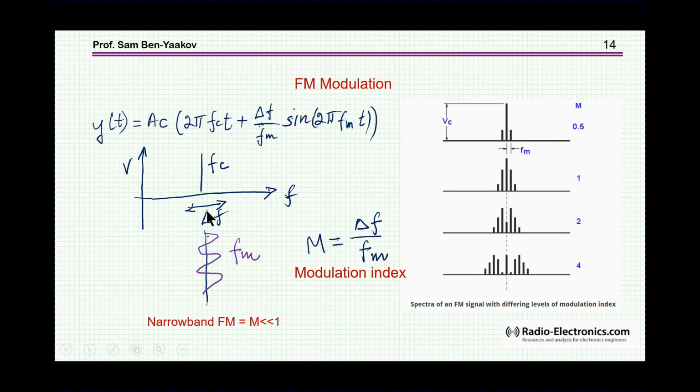The deviation is affected by the signal we are feeding in, the excitation. So we would like to keep it small. Of course, we have to worry about signal to noise ratio so that the ripple will not be too high. But we like to have this excitation small. First of all, because of the sidebands. Secondly, this is a nonlinear system, and when the excitation is very large, you might expect some distortion.